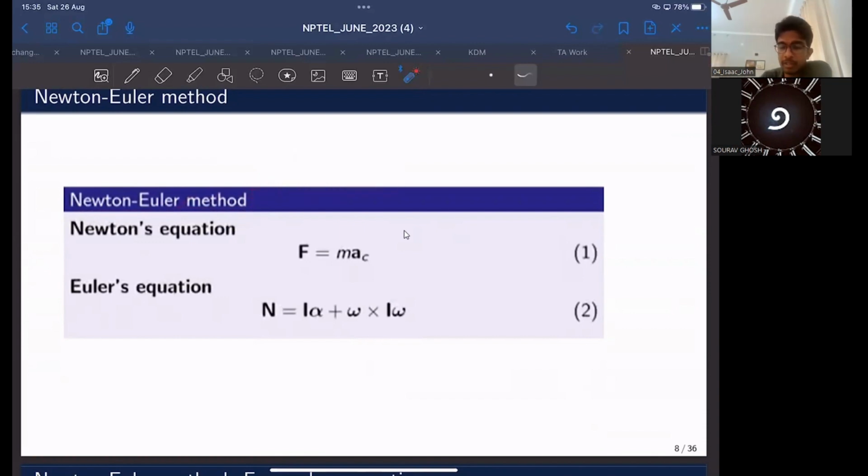If we find the velocity of the current link, we can use propagation equations to find the velocities of subsequent links, using this forward propagation. And if we know the forces acting on the end effector, we can successively find all the forces acting on the joints, coming back from the end effector all the way to the ground frame using this backward recursion.